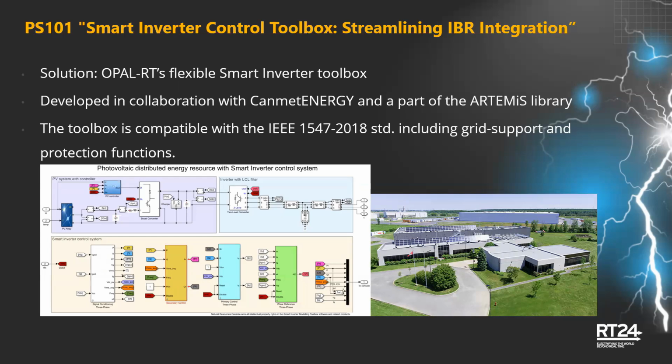For now, I'm going to focus on the primary and secondary level of control, namely how we can make it so that our renewable energy is properly working in grid following mode, providing PQ support, PV voltage support as well. These are the things that I'm going to focus on, and these are what are going to be demonstrated in this demo.